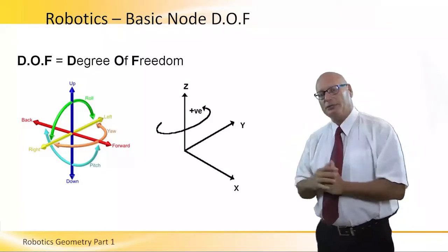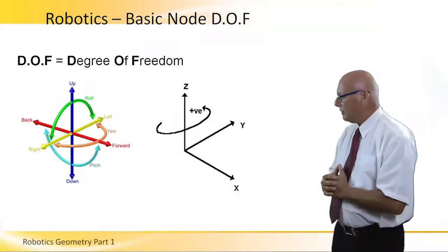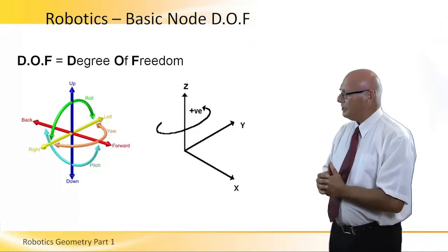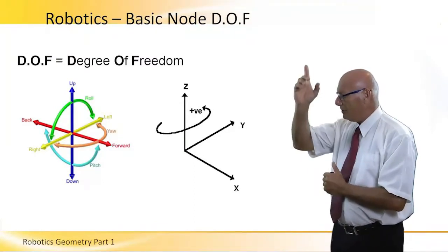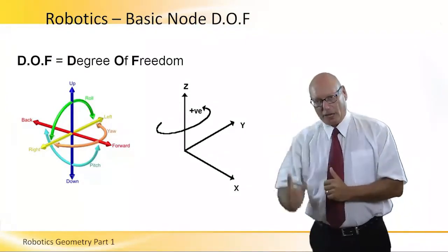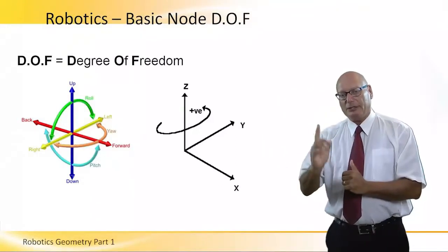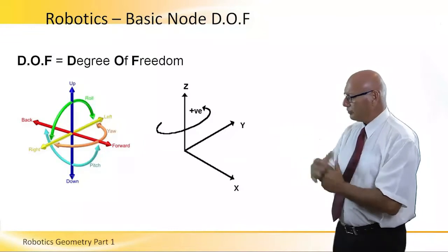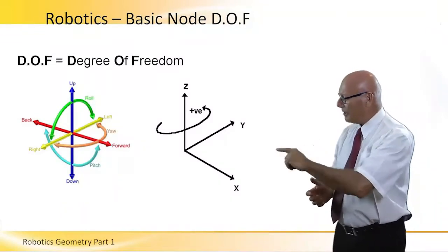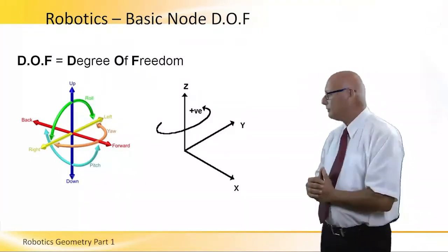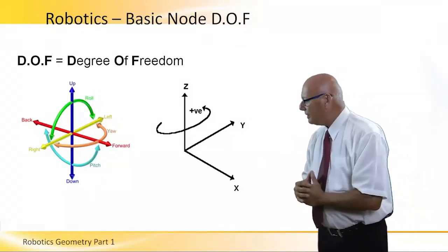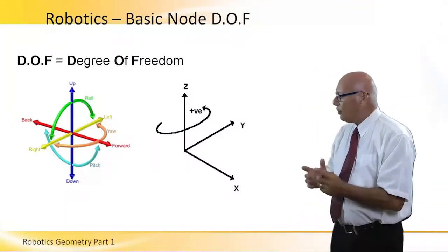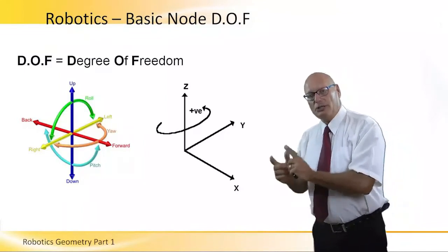We've covered the articulated robot in previous sessions, but here we can see that there is 1 degree of freedom in dark blue, covering the rotation and the going up and down of the joints of the robot itself. In red, we have back and forward, which is another degree of freedom. Yellow is right and left. And then come roll, pitch, and yaw.